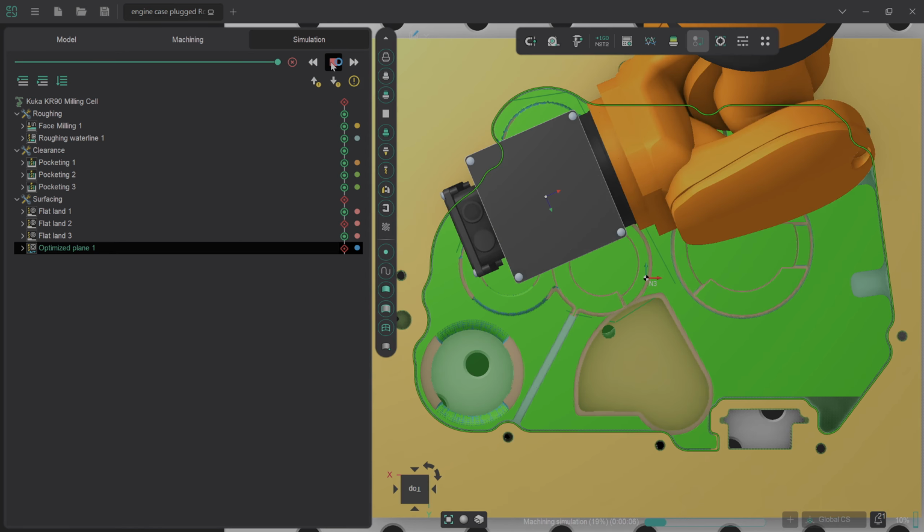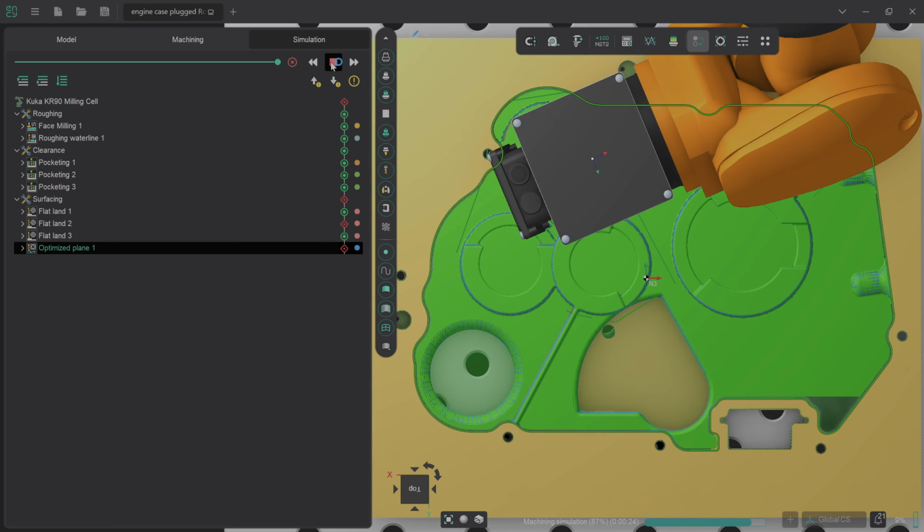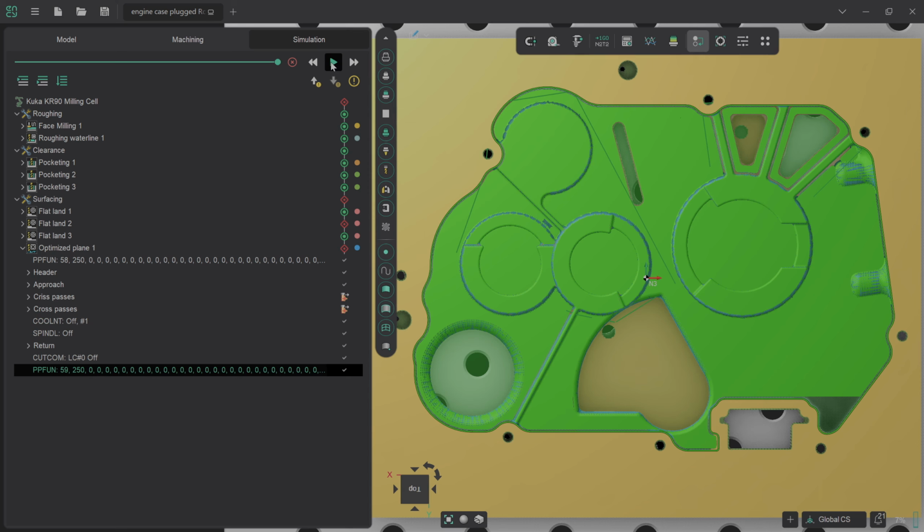You may find yourself wondering why I've gone for an optimized toolpath instead of a complex toolpath. The reason for that is there's not really enough of a Z value in any of these component parts to warrant using a complex toolpath. Because that's a hybrid between a planar toolpath and a finishing waterline style toolpath, it really does need a bit more height variance to capitalize on it fully.